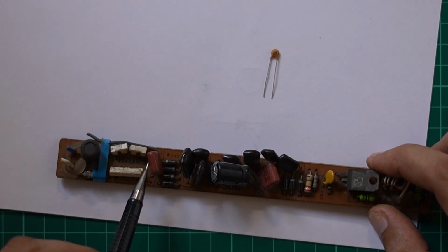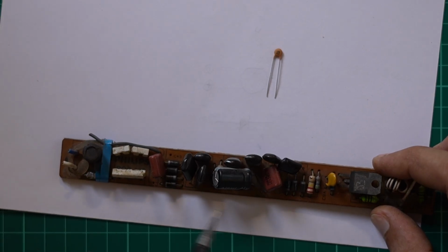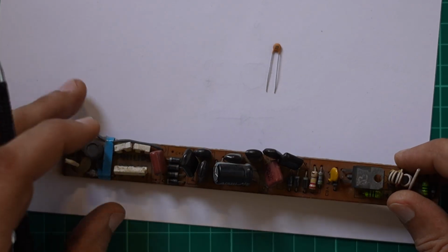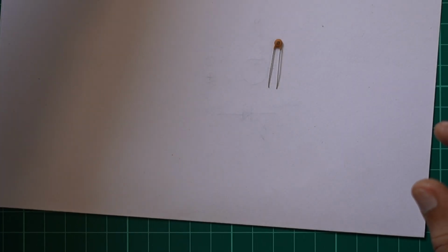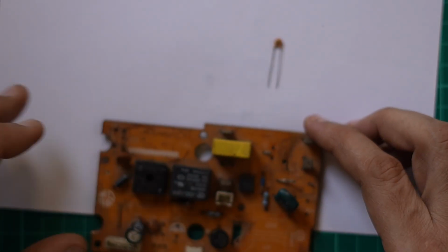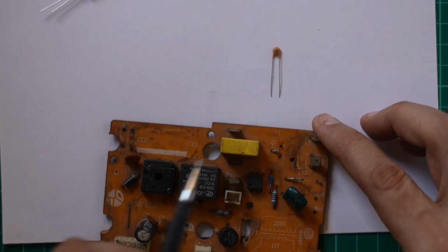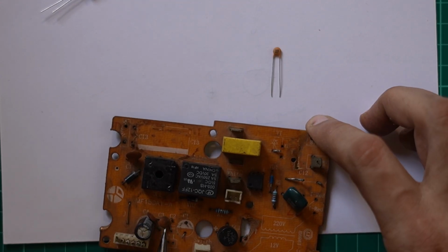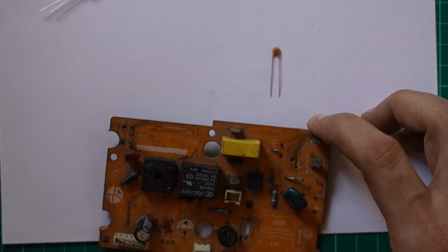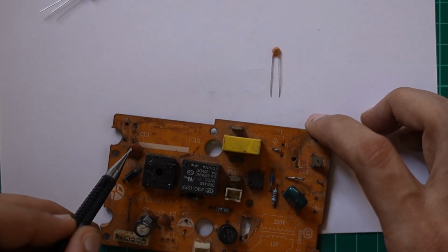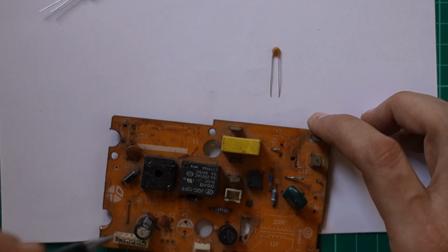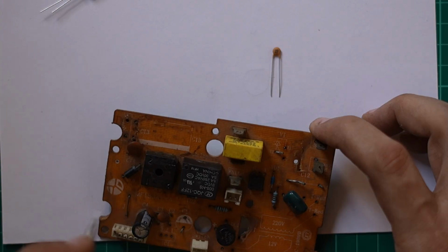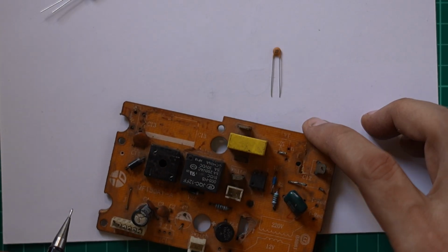Here's another capacitor, here's another one, and you can see the circuit is populated with lots and lots of capacitors at different points along. Here's another old circuit I picked up. This has just another capacitor. Here's one over here. Here's a second, here's a third one. Here's one more over here, one more over here. So you can see these little disc capacitors, they are all the noise or the decoupling capacitors, and the bigger ones are for filtering purposes.